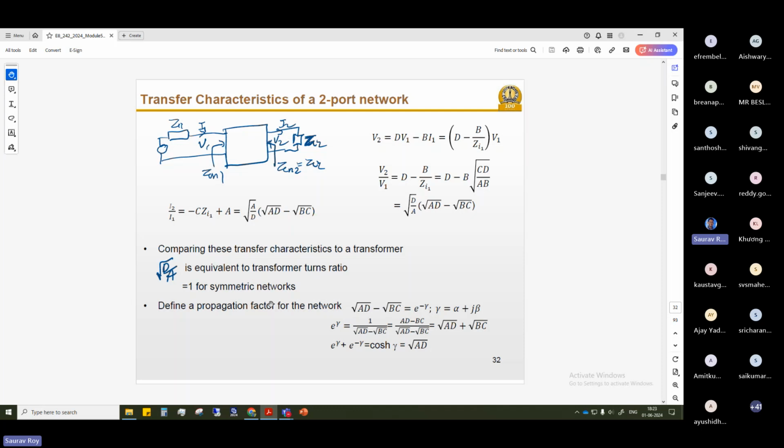Then in the same circuit you can replace the elements with microstrip line sections. Then it will be compatible with the normal microwave circuit. But for the basic theory of microstrip, you need these ABCD parameters. That is how it is explained.